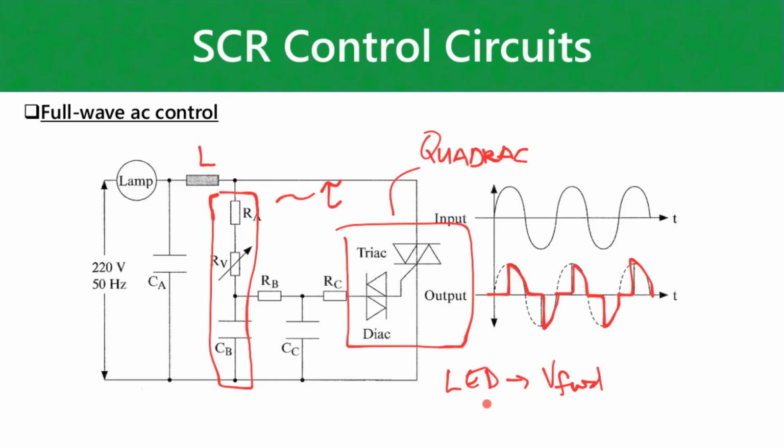Now, essentially what you need to do with an LED is find a way to change the current flowing through it. There are a few ways that you can do that. You can insert an adjustable resistor in series with the LED, which is not ideal because it wastes a lot of power. The other way is by changing the average voltage, which is going to change the average current.